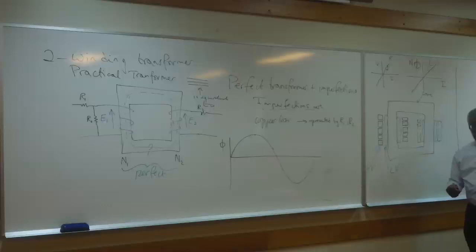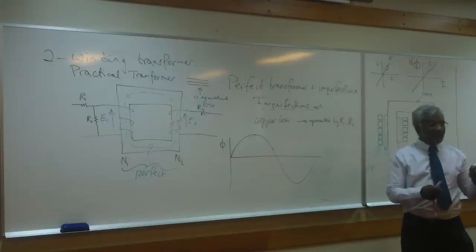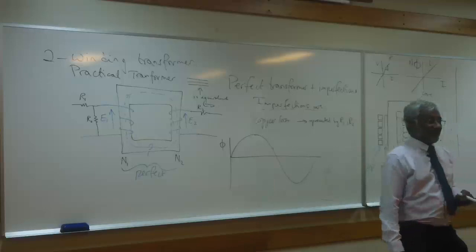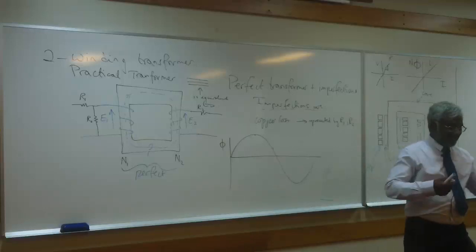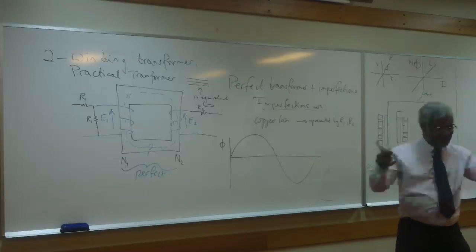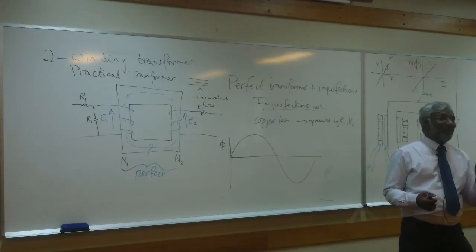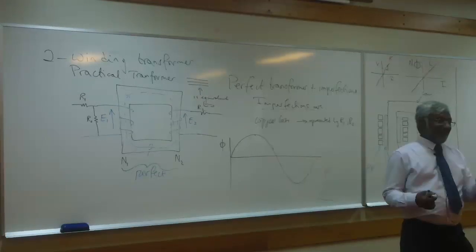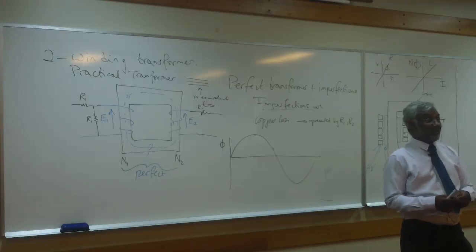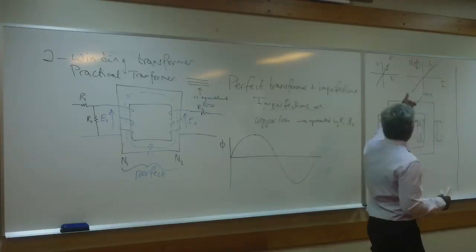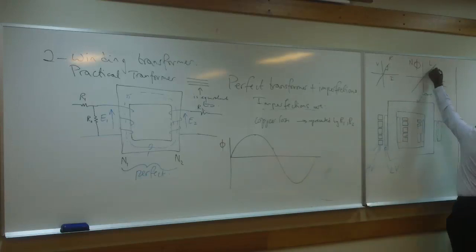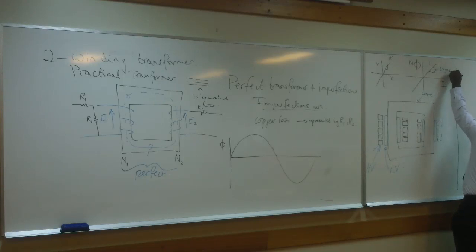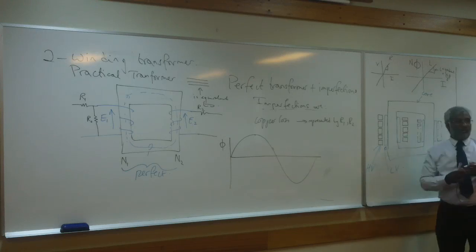So something has more inductance if we get more flux when we put 1 amp into it. That's why with a coil with many turns, you put 1 amp into it, you get a lot more flux than where you have 1 turn. If I have a piece of iron next to it, then I will push the inductance up because I need less current for the same amount of flux, and so on. So that's the definition of inductance. So the inductance is the gradient of this line. So L equals the gradient, equals N phi divided by I. Amount of flux linkage per ampere.